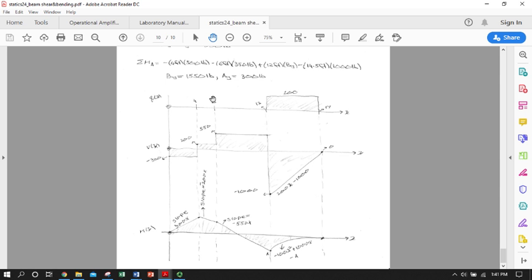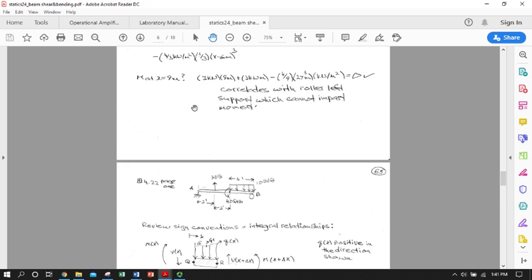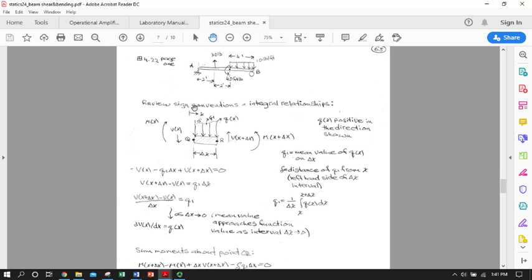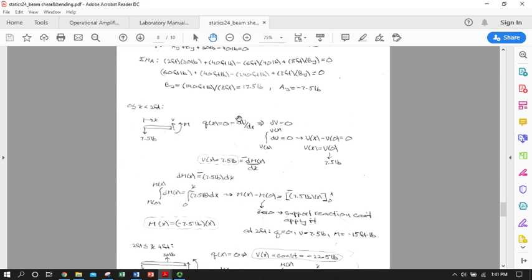So that is it for this lecture, and I hope you can see that even though there are a lot of different valid ways of approaching these shear and bending type of solutions, the definite integral, I think anyway, is the easiest and most bomb-proof, where you write the relationships between your distributed load and your shear, or your shear and your moment as differential expressions, and then just integrate each differential and use that fundamental theorem of calculus on one side, and then use that lower limit to roll in both the endpoint of the previous section adjusted for any points that you pick up as you head into the next section.